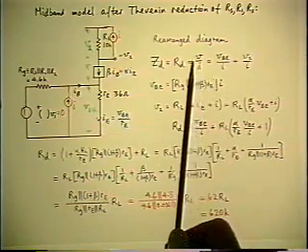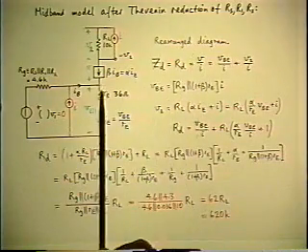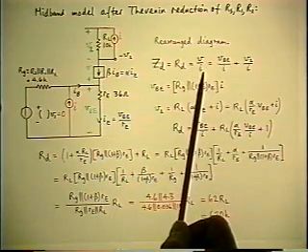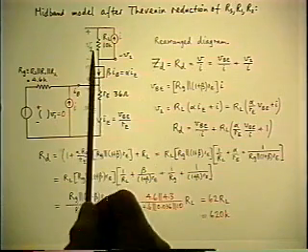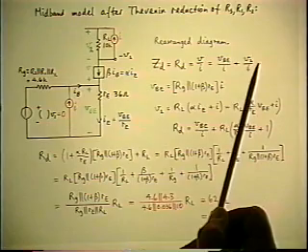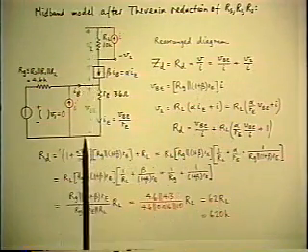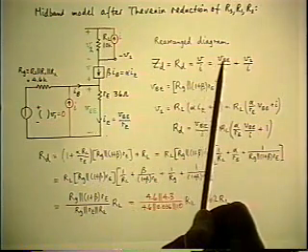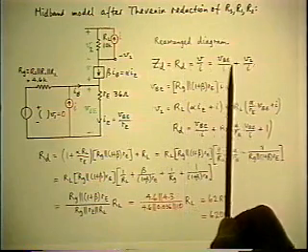So, let's just walk through the steps just to describe what the process is. We're trying to solve for the green V divided by the green I. The green V is equal to the sum of VBE and V2. I should say that the algebraic sum of all three of them is 0 because we got AC ground at the top and the bottom. Okay, so I can separate the RD into the sum of two terms.